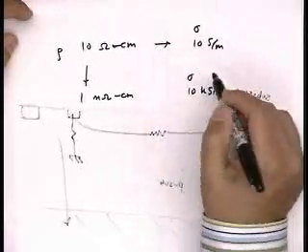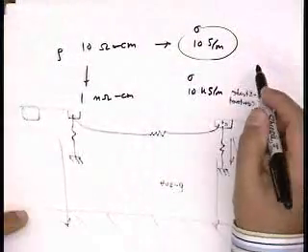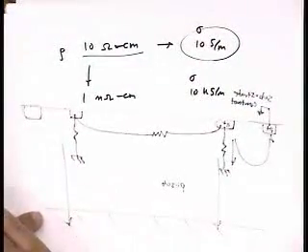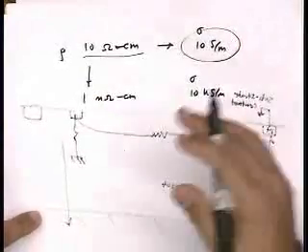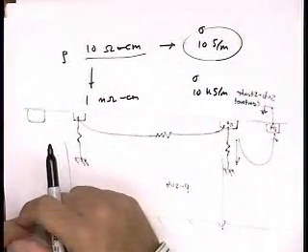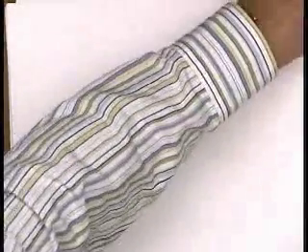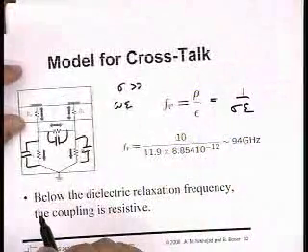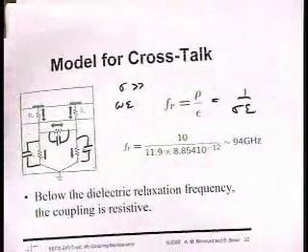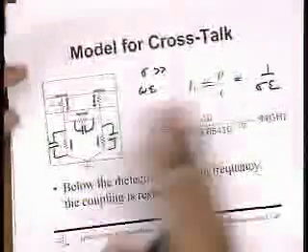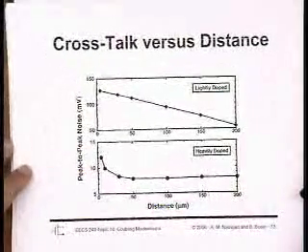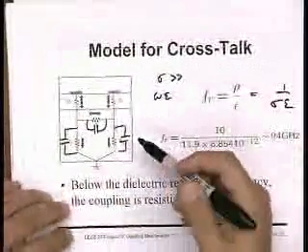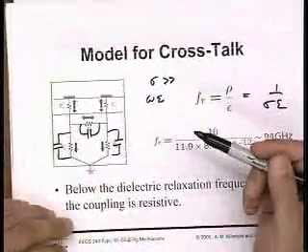So for the case that we've studied, this is the worst case. The non-epi substrate is the worst case. And even that, if you plug in the numbers, you get like 10 gigahertz. Well, you can just, it doesn't really matter, right? I could just move rho down here. But trust me, I've run the numbers, and it works out that for the range of substrates that we care about, it's not an issue. Okay? All right, so this model is really simple, but it's also very intuitive, because it tells me that, let's